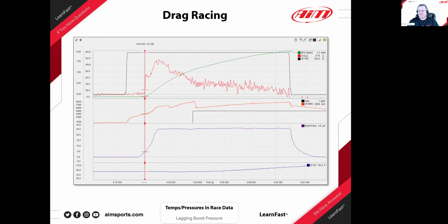And that's why you see the water pressure sensor. I did not ever want to blow up another motor for a silly reason, right? Of a pinhole that ends up draining the water and we didn't know it. The rear diff temperatures, all of these different things. And maybe early on it was steering. We really wanted to understand exactly what the driver's inputs were in order to help him become better.